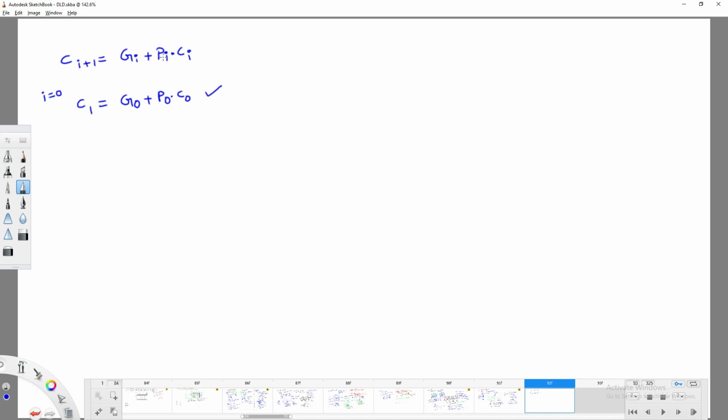Okay, what is Pi? See, A0, A1, A2 and A3, B0, B1, B2, B3, right? Here you are going to get C0, so there is no problem. A0 and B0 means, what is Pi here? Pi means Ai XOR Bi.